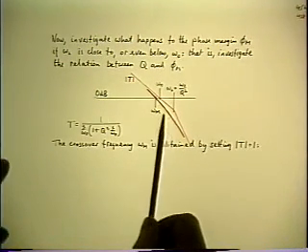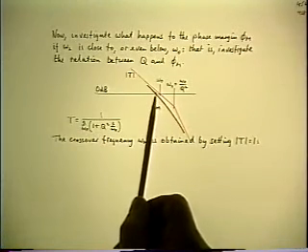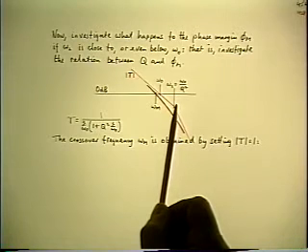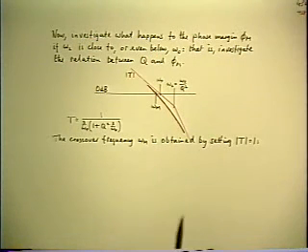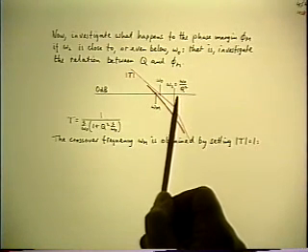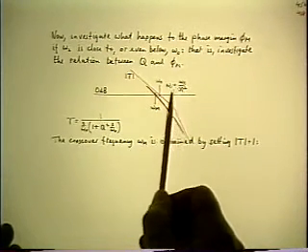So the first thing we do is evaluate the crossover frequency in terms of the position of the second pole. It's useful to have the Q as a parameter now instead of the omega 2, because the Q is the quantity that comes up in the answer we're interested in, which is the shape of the D. So let's substitute the variable.